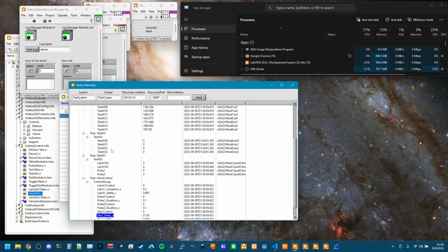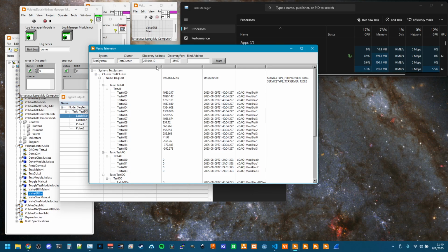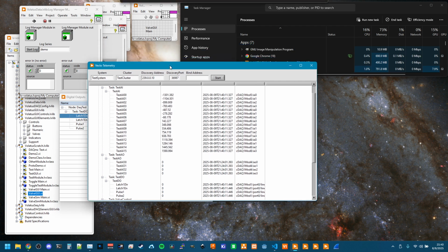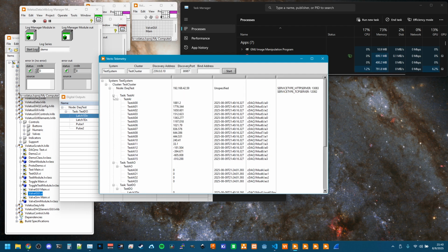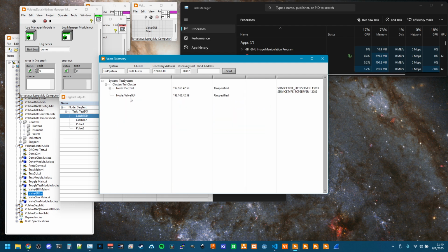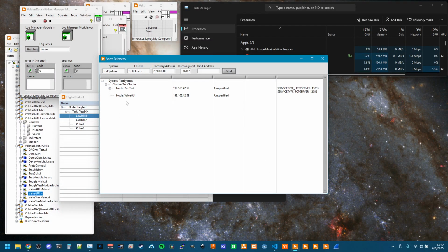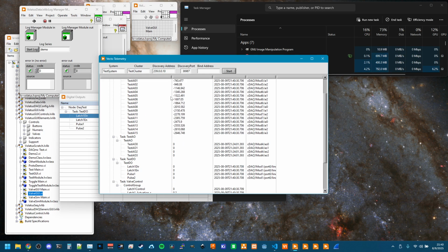And do I have it up? Yes, I've got the telemetry debugger up. And this is some generic tooling that queries the application for what channels it has available, and then it can start receiving it. This only updates about 5 times a second, if I'm not mistaken. But we could see the 2 applications that are running, the DAQ test node and the GUI node. The GUI node has nothing it's publishing, no value it's generating, so there's nothing listed there. And just like the other generic GUIs, we could see all of the analog input tags getting updated.